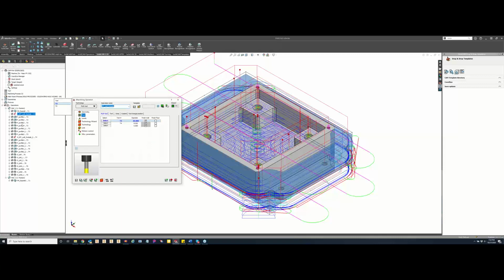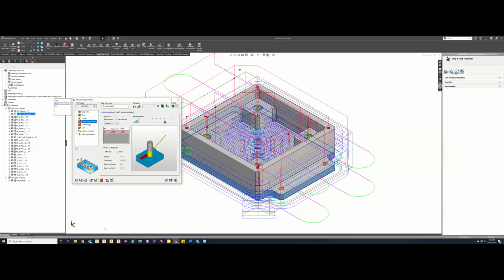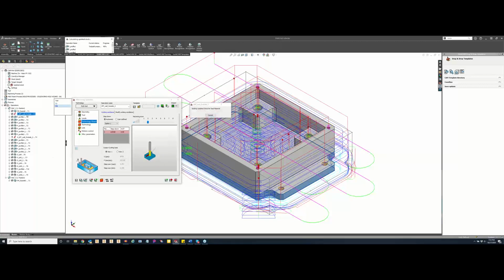Okay, so now we have them completely separated out here, and let's just do our technology wizard. We'll run tool number 2 at level 6, as well as tool number 4 at maybe a level 2. Save and calculate. And you'll see that it is updating. It updated the first one, and it's going through and updating these files because it is all based off of updated stock. So we have to verify the stock left over from these, and then it will be calculating our last.